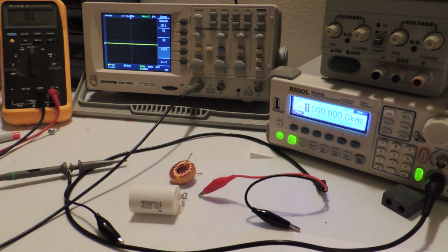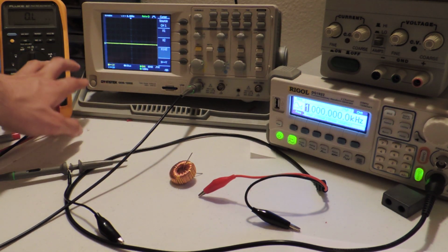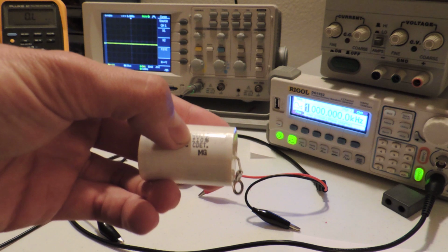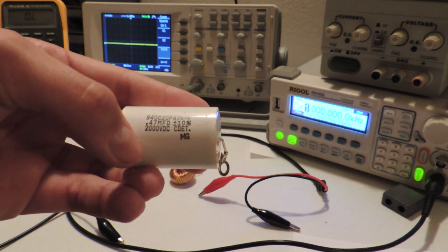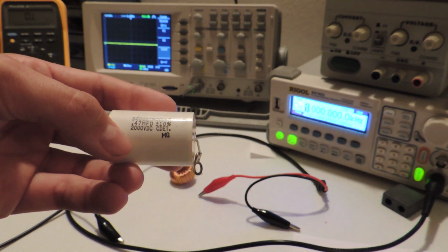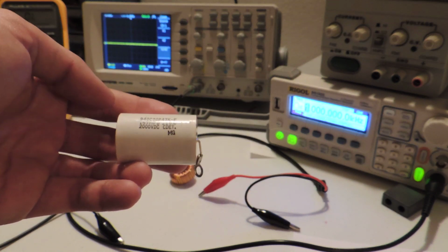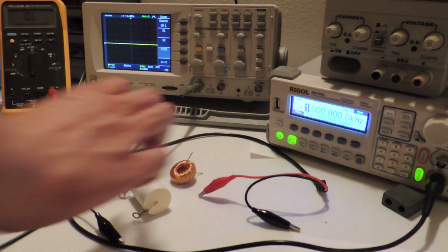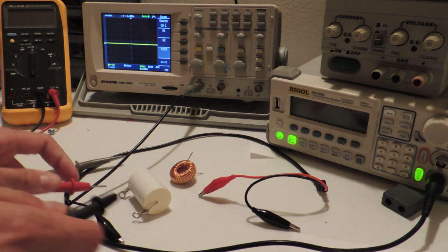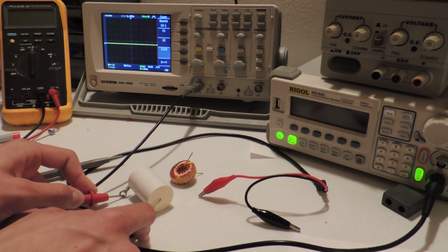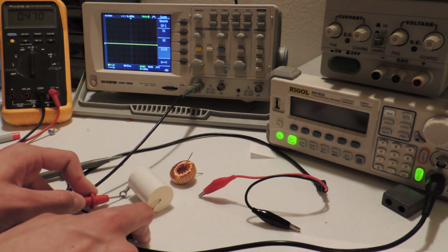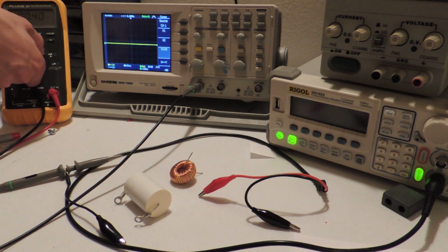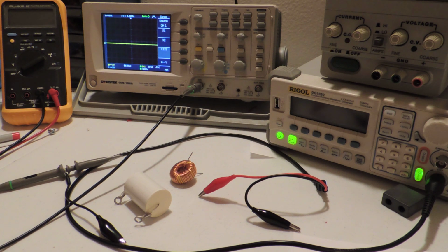So let's start with C. The reason I recommended that you get a meter like this instead of just relying on the value printed on the capacitor is that most capacitors have a tolerance. In this case, for this cap, it's plus or minus 10%. If we do not measure this capacitor and get an accurate value, that 10% error will show up in our final measurement. So, as of right now, we are going to check the capacitance of this cap. And it comes out to 0.47 microfarads. So that is the number that we will use in our final calculations when we get the frequency.